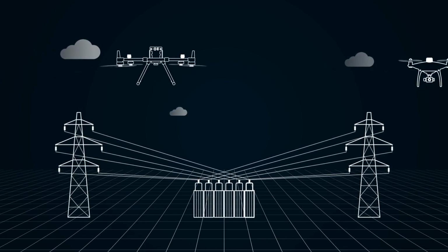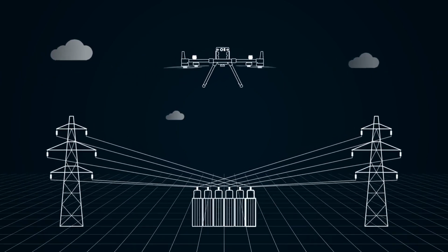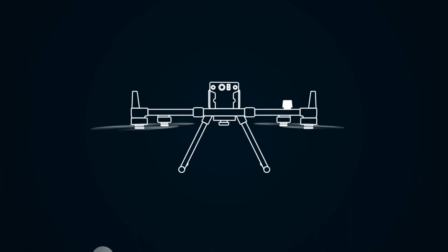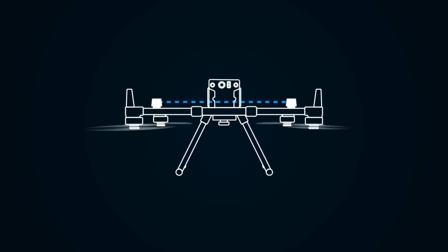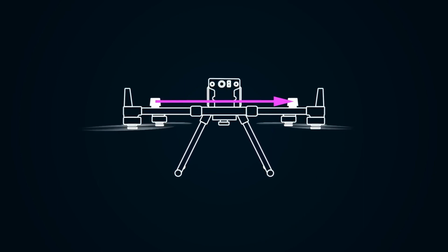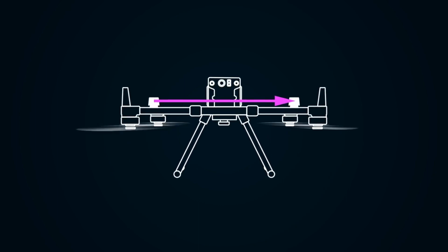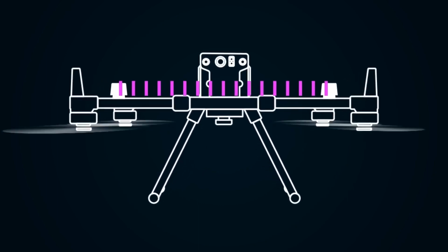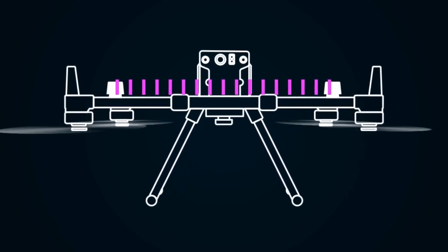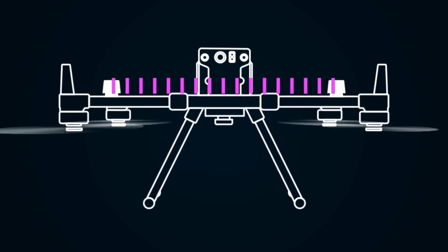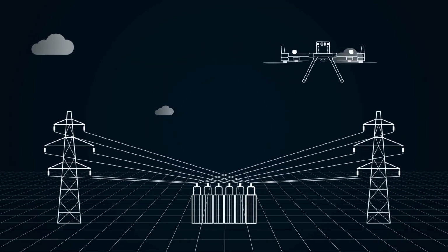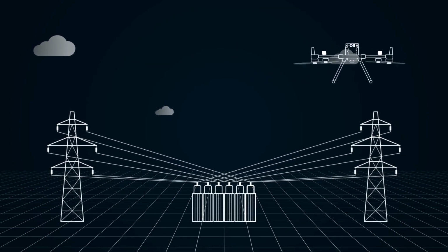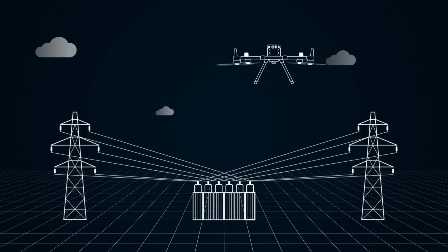DJI Dual Antennas Tech could solve this issue. By having a second antenna to send and receive signals, the drone will receive two sets of data from each of the antennas. Using one data set as the benchmark, it could calculate the precise locations of both antennas and accurate heading. The longer distance between two RTK antennas also leads to the more precise navigation of the aircraft. Above all, the development of positioning technique improves the positioning accuracy, mapping accuracy, and drone safety greatly.